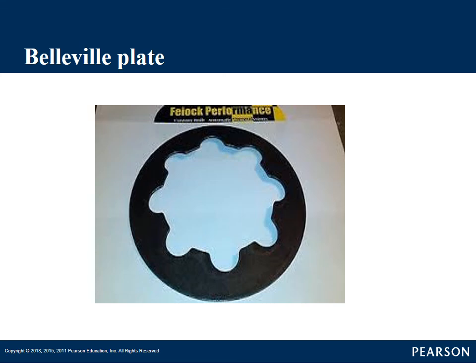Here is a beveled plate that I was talking about, a little better picture than the one before it. As you can tell, the inner diameter of the plate sits at a different level than the outer diameter, so it's beveled. That's where we get our name from. Again, these types of plates are used to help cushion the apply of our clutch packs. And if it has these plates in there, you've got to be careful on how we check clutch pack clearance.